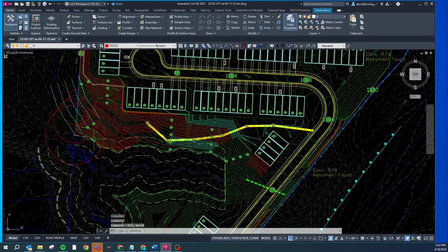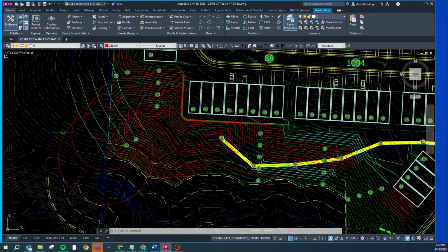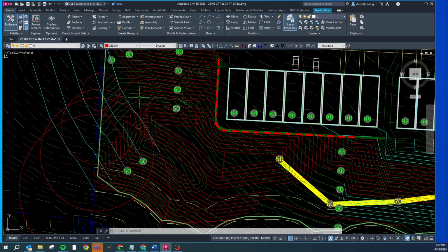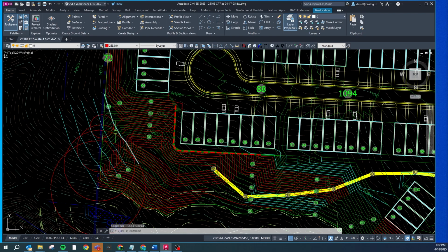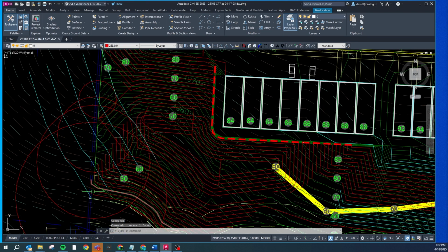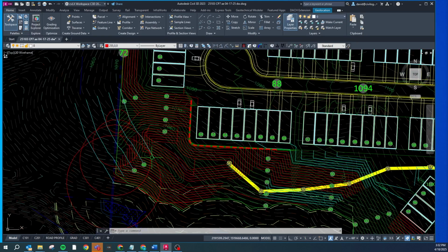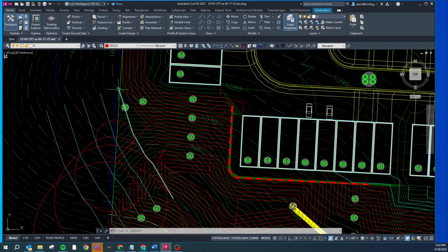The most efficient way is to just think strategically about the design and what needs to be accomplished using these general spot elevations. Here's another quick little technique I want to show you. If you want to not waste space next to a property line, you want to grade continuously, figure out if your contour lines need to generally go in this direction or in this direction. And in this case, we can choose that because we know we want to go from 30 up to 50 or 60 for the pond, and if the 50 or 60 is up here, we know it's going to go down in this direction. So start at the top.